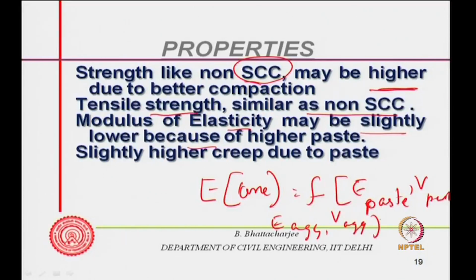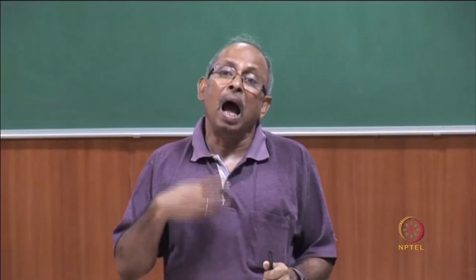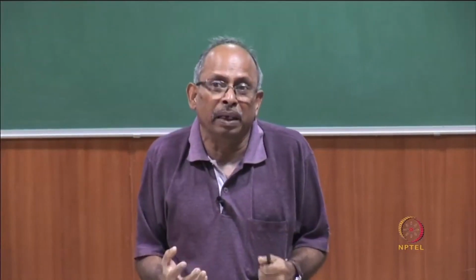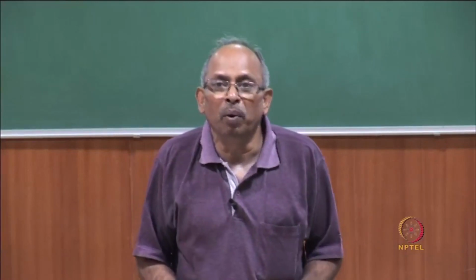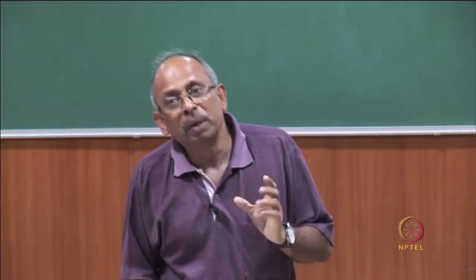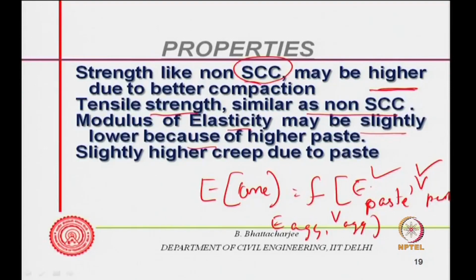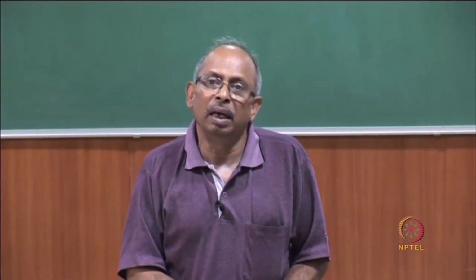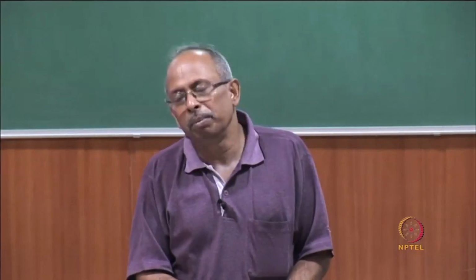So, since I am increasing V paste, it will depend upon E of the paste. It will depend upon the situation where E paste is high, that means in a high strength situation, if you have self compacting concrete, then modulus may not be lower. So it could be affected somewhat, slightly lower with higher paste content, depending upon E of the paste.